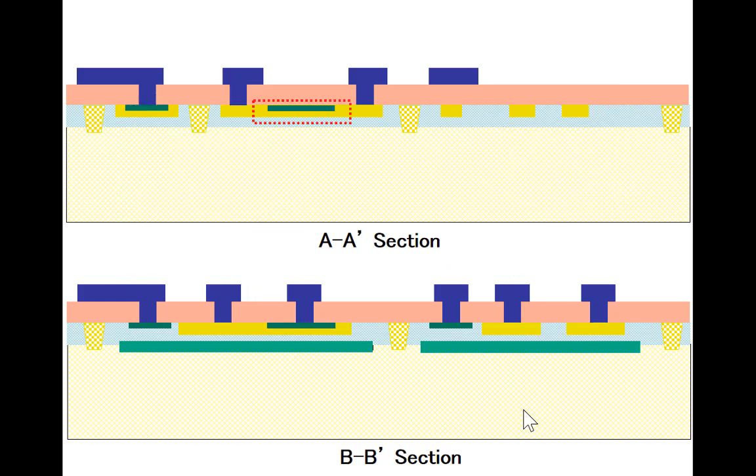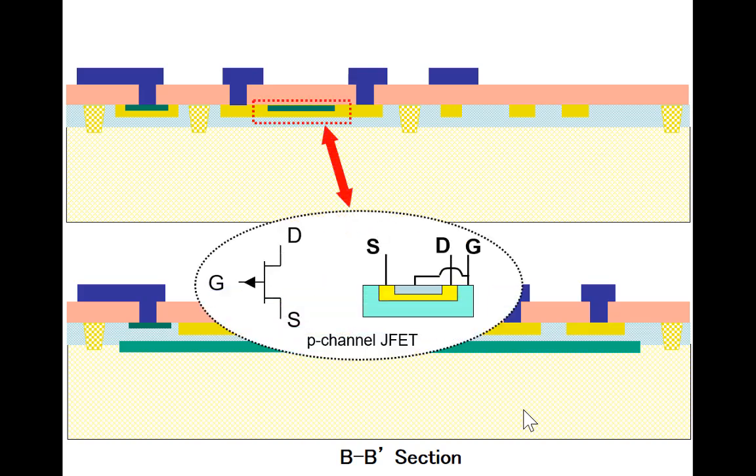Here's the JFET. Notice what happens here. We tie these two together, and this becomes the gate. As we change the voltage from the gate to the source, we will change the thickness of that P base region, and we can make it thinner. In fact, we can pinch it off, much like for a MOSFET. So current will flow through this base region, and we will control the thickness by the voltage between the gate and source, much like we did for a MOSFET.